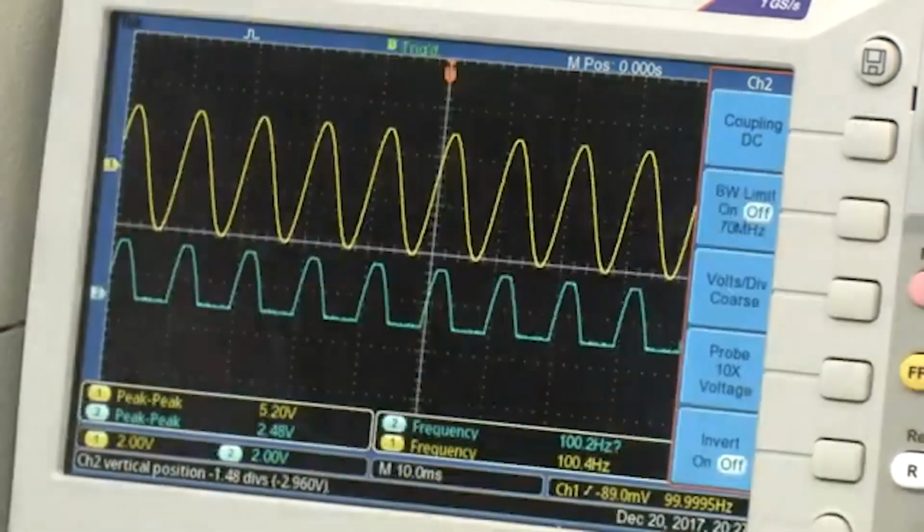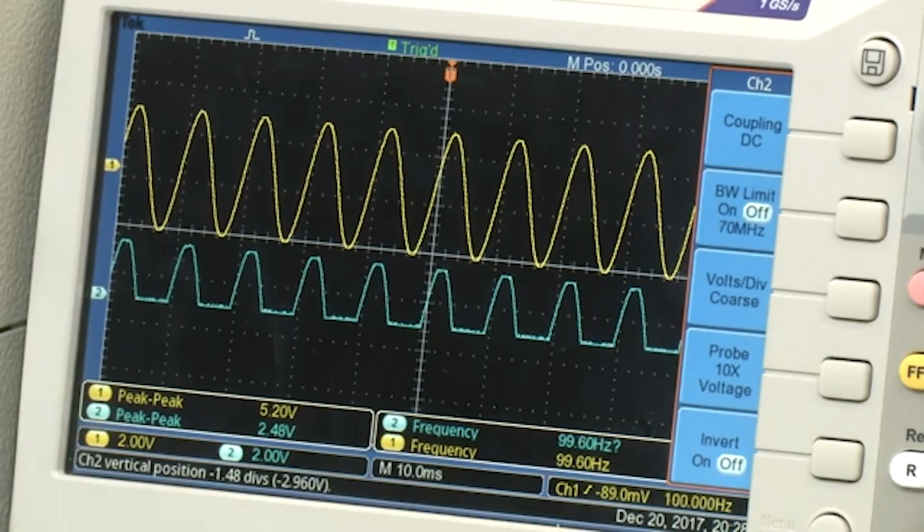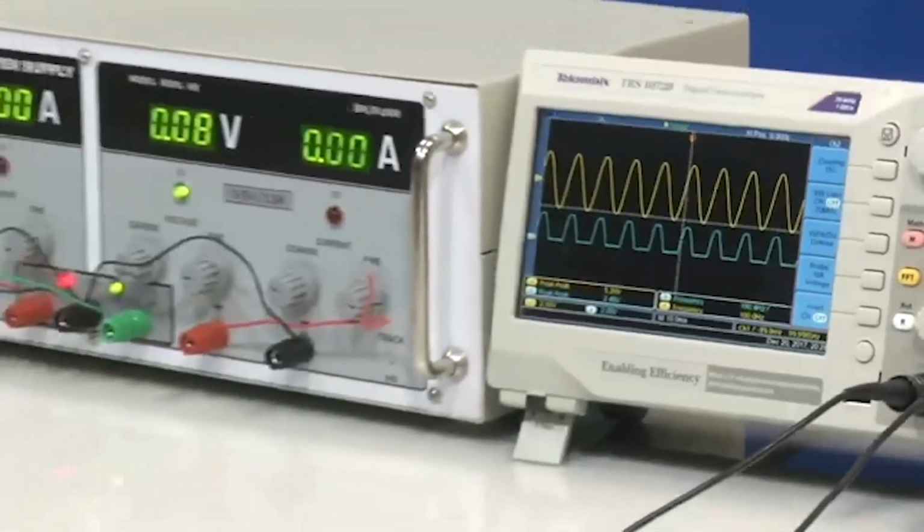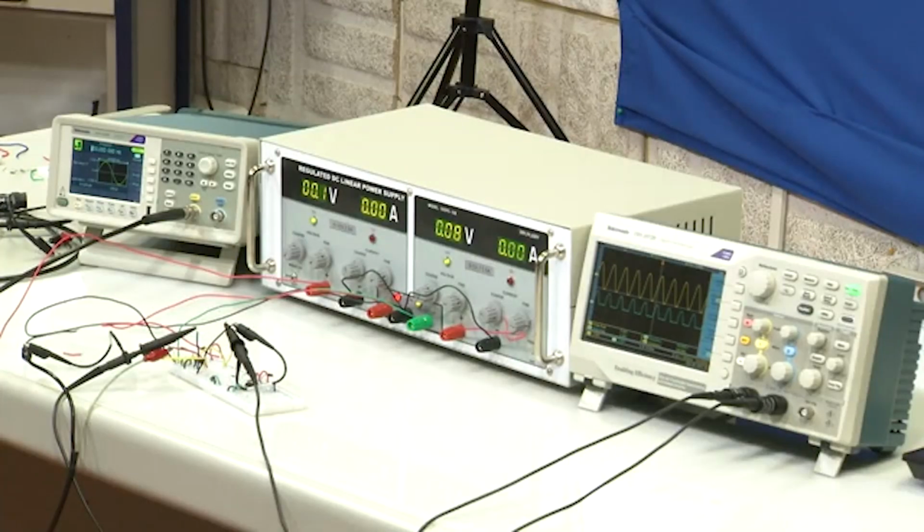that at lower frequency also we are able to see the half wave rectification. At different frequencies we are able to see half rectification, and the voltage is half of what we have applied at the input. So, same thing we are looking at in the case of the half wave rectifier: by using it we can rectify half part of the input signal, and if you want to rectify the full part we have to use another rectifier. So, the point is that this particular experiment tells us how we can rectify the signal.